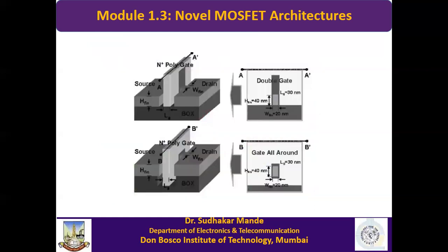Yes, sir. Now, there is another type of this. See, this is a double gate MOSFET, you can see. So the gate is on this side and this side. When you take a cross section here, what you see is the channel, basically, this portion. This is the top gate and this is the side gate, right? And this is your fin, substrate, insulating material.